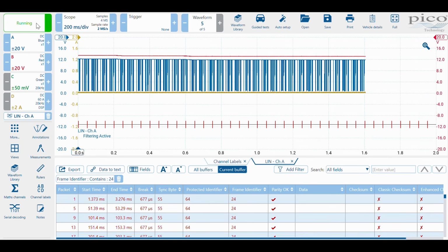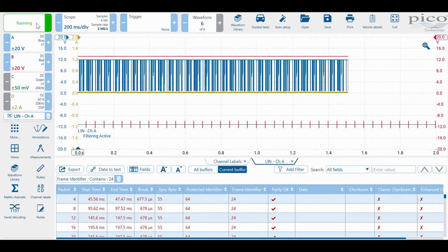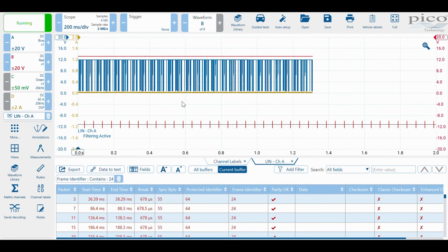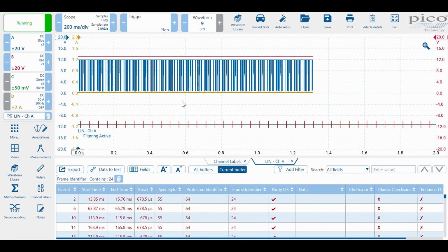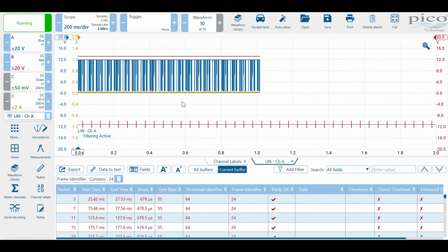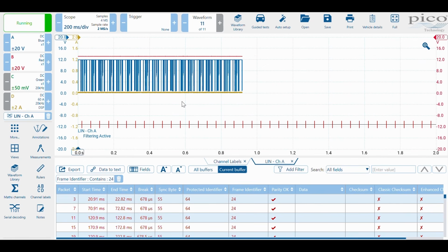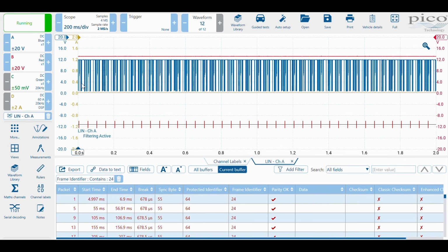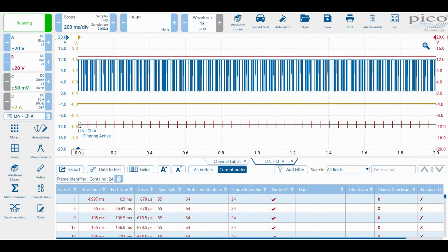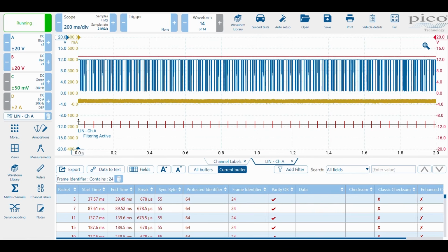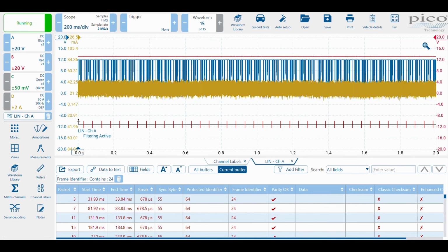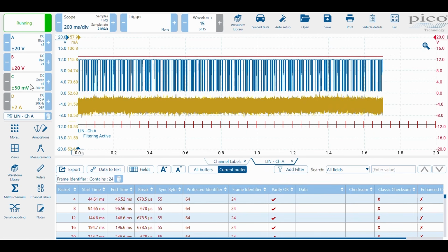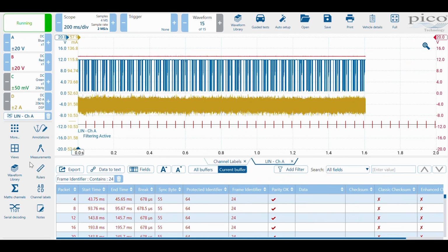Not surprising, because we've added such a high resistance in the ground that we can't pull that voltage down low enough to determine a 0 or a 1, or to define a threshold which defines a 0 or a 1. So notice now the current, well, let me just scale up on the current. We're not seeing those spikes. Not surprising, because there's no current flow, but also notice channel C. So let's bring channel C back.